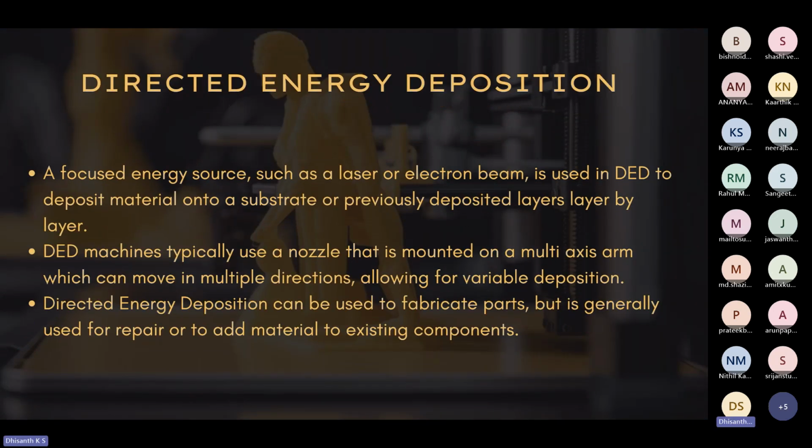Now, Kati will teach about directed energy deposition. Third, directed energy deposition, DED. The process is like this: a focused energy source, such as a laser or electron beam, is used in DED to deposit material onto a substrate or previously deposited layers, layer by layer.